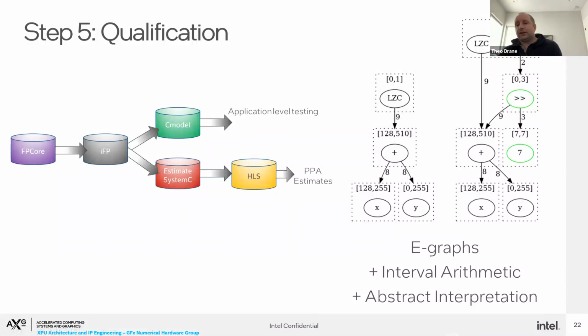So a slightly simpler question is, this is all ASIC targeted. But let's say I had one of those fixed block DSP things that can do, I think, 18-bit multiplication, whatever it is. Of course, you can wrap that 18-bit thing with modifiers, and so in theory it can do lots of different functions.